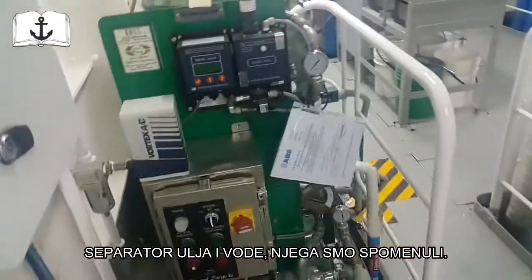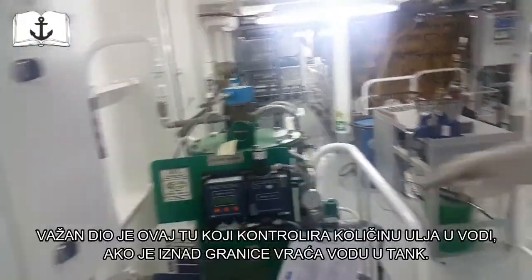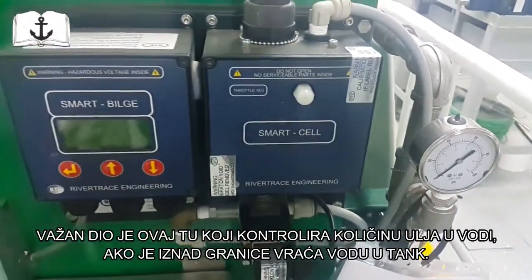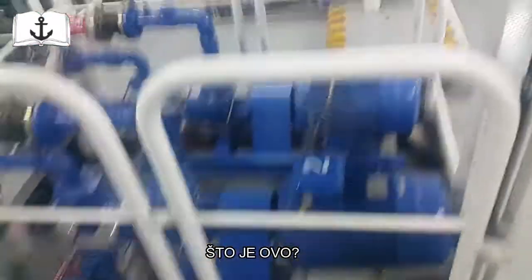The oily water separator, yeah, we mentioned that. It's separating the oil from the water. You have pumps, yeah, pumping. The important thing is this cell that gives you the alarm if the water is dirty. It's redirecting you back to the oily water tank. If it's within the limit, we can discharge.